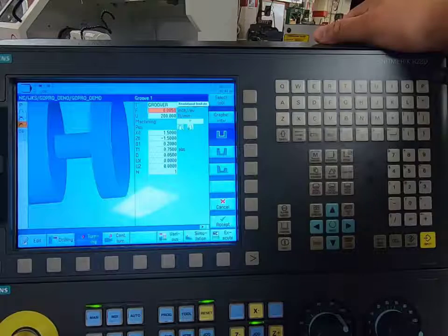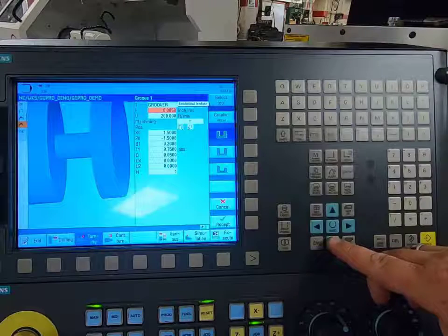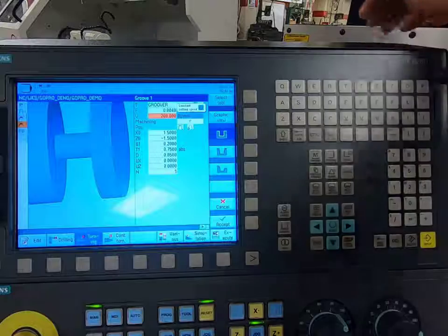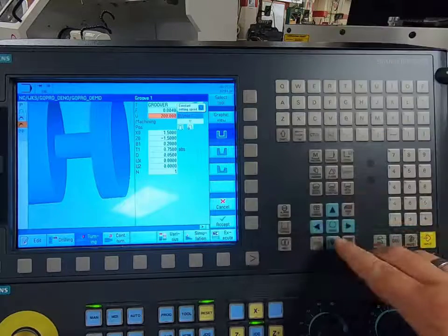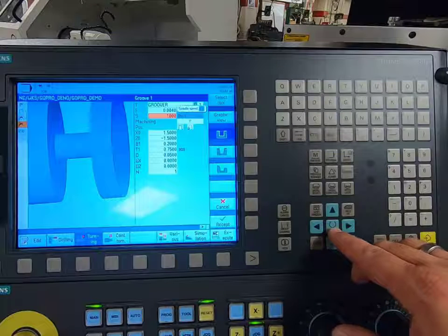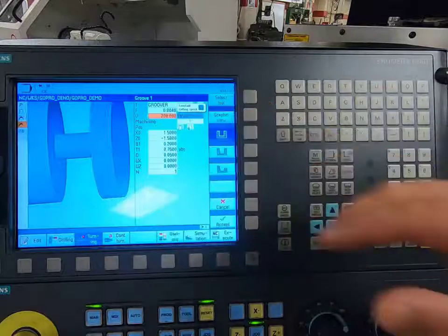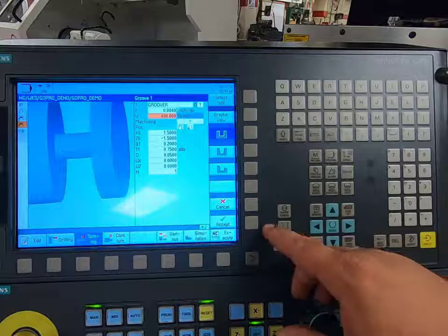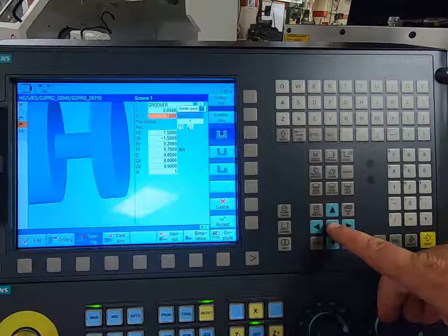Okay, my inches per revolution is at 5. Let's not go any higher than that. Let's change it to 4 so you guys can see it change. Now I've got a constant surface speed. Notice how I changed it just a little bit because I don't want my part flying out on me. Or I can change it, like I said, to a constant RPM. Now when I type a variable in here, say I type in 400, and then I come up here and I hit RPM, I can change it right back to the same RPM.